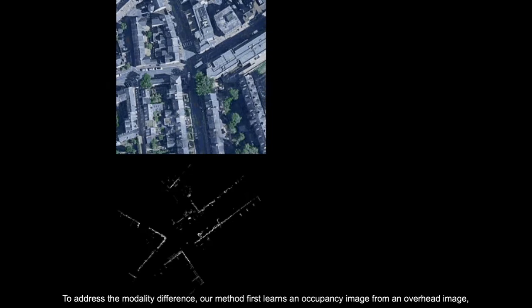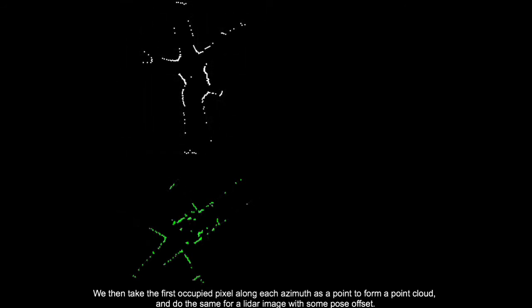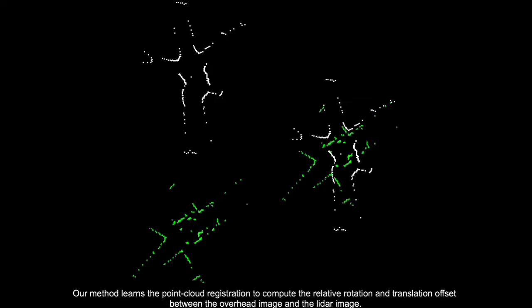To address the modality difference, our method first learns an occupancy image from an overhead image, where the pixel value indicates the likelihood of each pixel lying on occupied space or free space when scanned by a LiDAR sensor. We then take the first occupied pixel along each azimuth as a point to form a point cloud, and do the same for a LiDAR image with some pose offset. Our method learns the point cloud registration to compute the relative rotation and translation offsets between the overhead image and the LiDAR image. After predicting an occupancy image and subsequently converting into points, our method learns a global descriptor for each point set.